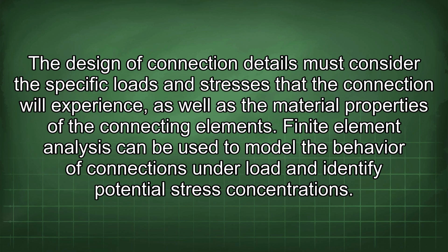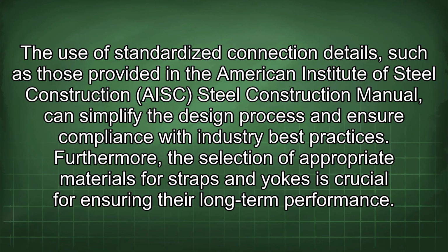Finite element analysis can be used to model the behavior of connections under load and identify potential stress concentrations. The use of standardized connection details, such as those provided in the American Institute of Steel Construction (AISC) Steel Construction Manual, can simplify the design process and ensure compliance with industry best practices.